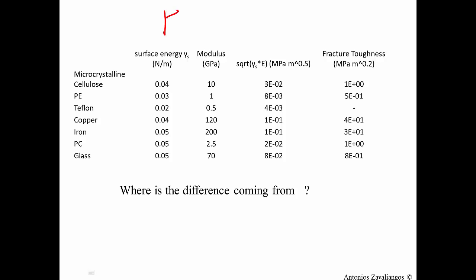I'm referring to the estimate of the fracture toughness as given by this formula, the square root of 2 times the surface energy times the elastic modulus of the material, which reflects the two aspects of crack propagation that we have analyzed up to this point.